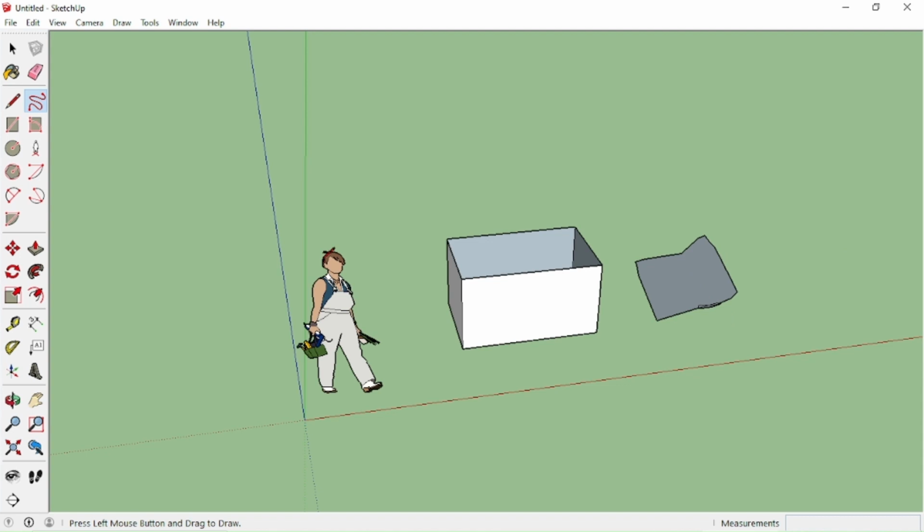You could use your freehand tool for that one. And then the next tool we're talking about is the arc tool. I know some people wonder why I like this one. We'll be covering it one after the other. So the arc tool creates an arc or circle. To create an arc, you click once, and then when I click, the arc is not moving anymore. It has selected the center point. By clicking somewhere else on the other point, it shows the program that here is where you want to start your arc from.